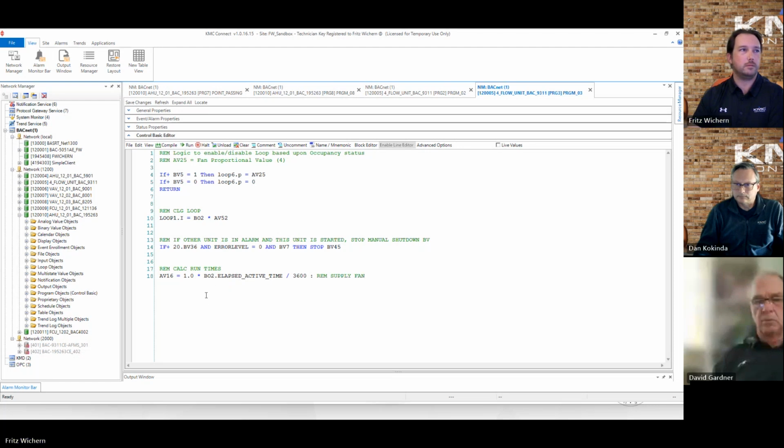All right. A couple of questions came up. Is setting the integral value in a loop to 0 a reset? Yes, it actually resets everything to zero, so you're starting from scratch. So that'll reset the I portion to zero, and you'll start from scratch.